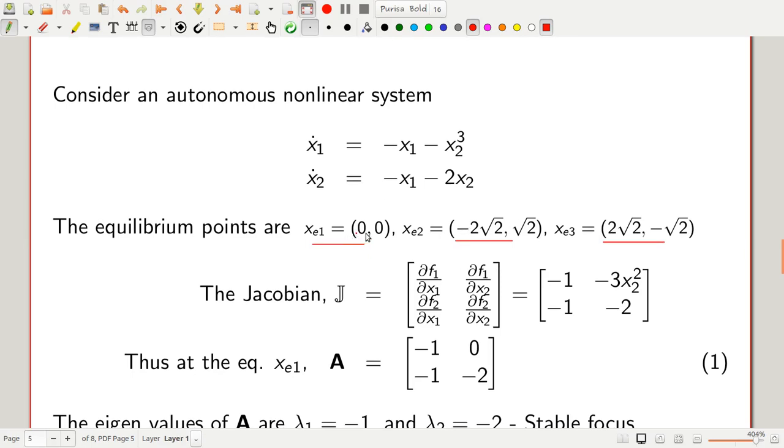Okay, so first let us speak about the stability of the equilibrium point about the 0 point. We are going to bring in a small perturbation about the equilibrium point xe1. So what is the process? What is the equation? We have delta x dot is equal to A into delta x, where A is the Jacobian matrix at the equilibrium point xe1. First we will form the Jacobian matrix, which is common for all three cases.